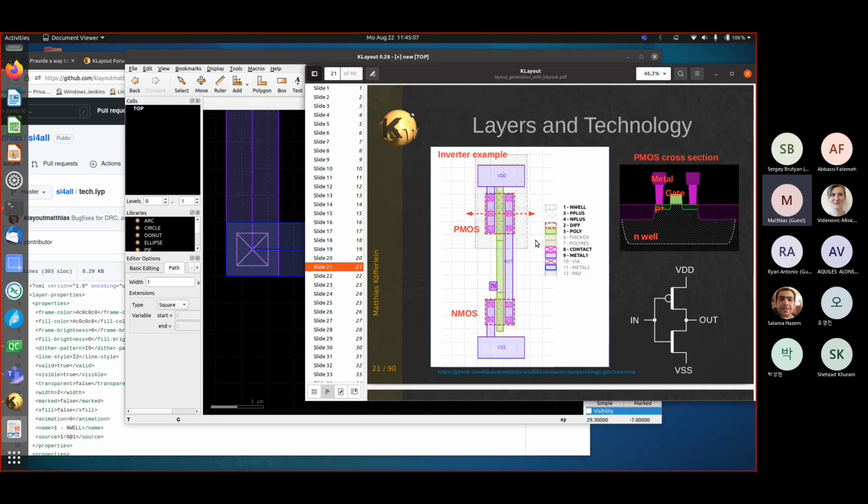Design rules are basically the law you have to follow to make your chips work. A process cannot go below a certain dimension, for example, just because the lithography will not allow you to go below a certain line width. It has to be made sure that your layout is conforming to these design rules.